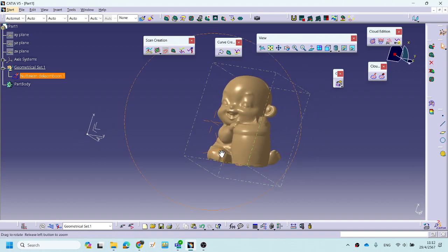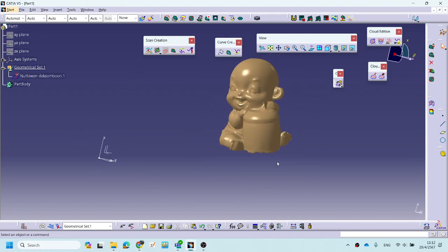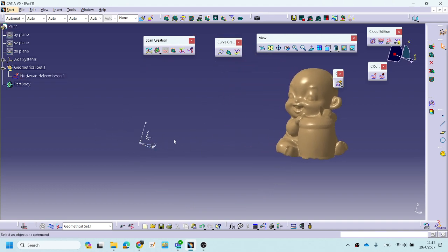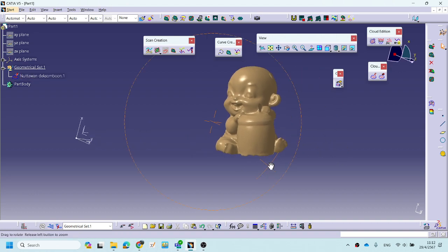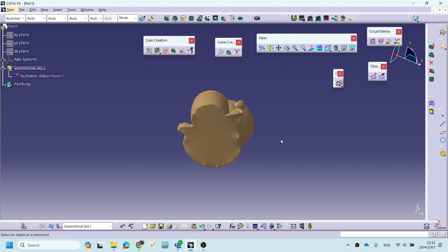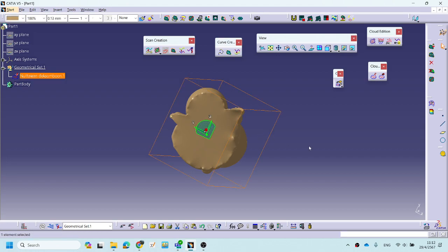I need to move your workpiece axis close to the absolute axis system, right? I will use the compass. Okay, you drag the compass point to the bottom surface of the point cloud like this,